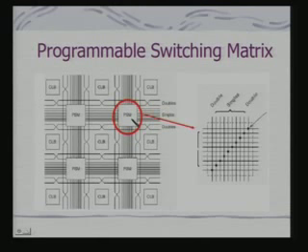So, when you are looking at the problem of designing an accelerator, it means the function which is to be implemented in hardware has to be mapped to the FPGA. If you are using mapping tools straight away, then what do you need? You need to encode your function in VHDL and use the tools to simulate and find out first whether your VHDL code is correct or not.